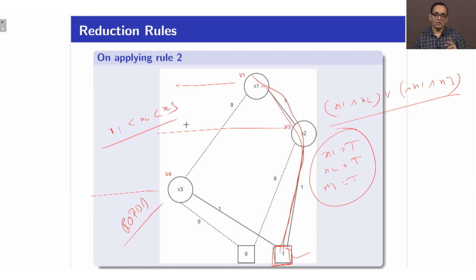But if you take a bad ordering, your size of the BDD will be exponential. So, the construction of the BDD will take exponential time itself. So, the satisfiability may be polynomial time, but construction itself takes exponential time. So, overall time is exponential, right. And unfortunately, given a formula, you do not know which is a good order, right. So, identifying the good order for which the ROBDD size will be minimum is an NP complete problem. So, effectively it is back to square one, right.